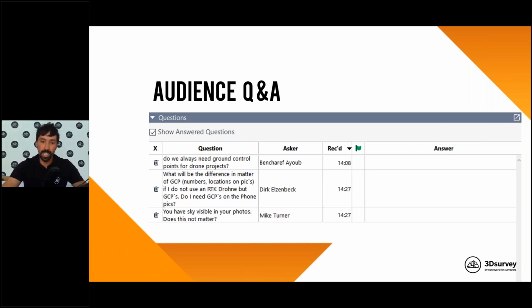For such a small object like here, I would use 5 ground control points, or at least 4, one on every corner, and it would also be accurate enough. There's no need for those ground control points to be visible on phone images, because phone images are connected with tie points to drone images, and after we orient the model and mark the ground control points on drone images, the phone images are connected with the drone images immediately, even if you have no phone images with ground control points. So there's no need for it. The bundle adjustment step does everything automatically.